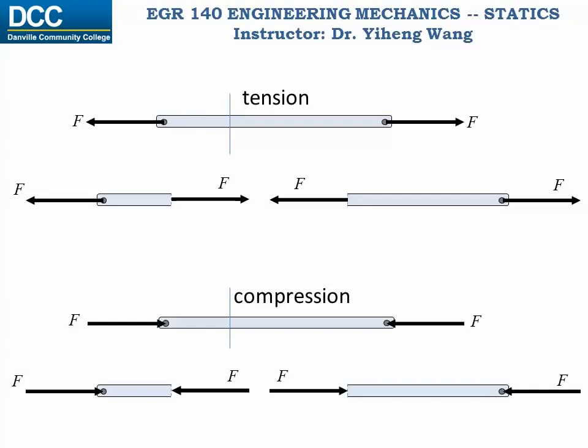Since, if you recall, one 3D rigid body free body diagram enables us to solve for a maximum of 3 unknowns, if we only need to solve for the forces in no more than 3 truss members in the structure, we can imaginarily cut the structure open and apply rigid body equilibrium analysis. This is known as the method of sections.